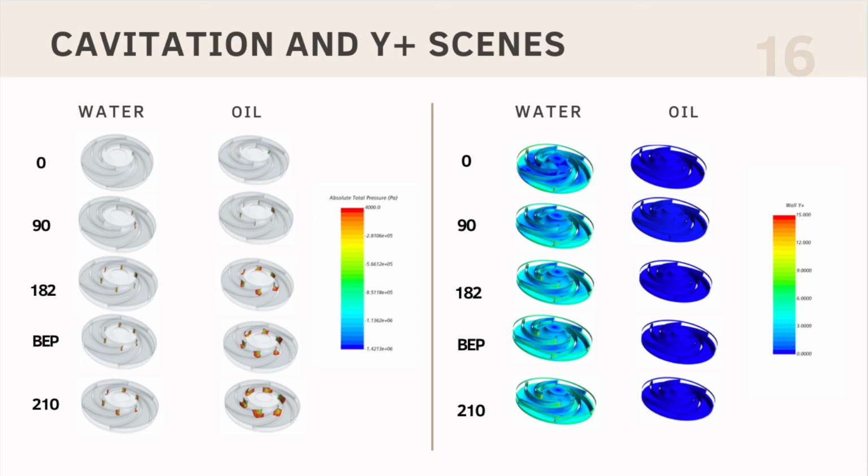Cavitation is an undesirable phenomenon and should be avoided because it decreases efficiency and it can cause damage to the impeller structure. Moreover, it can be observed that for both fluids cavitation increases as the mass flow increases. Comparing the substances, greater cavitation is obtained for the oil. This is explained from the properties of the fluid such as viscosity and surface tension. The difference lies in viscosity values. In more viscous liquids, bubbles collapse on themselves, causing structural instability.